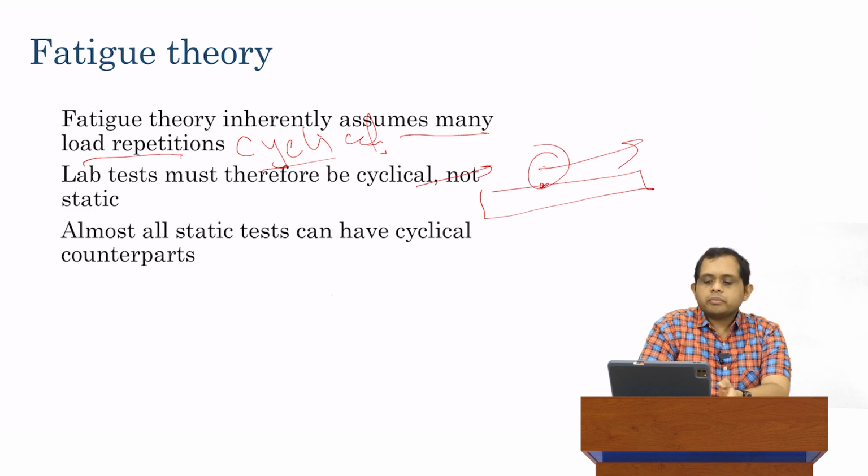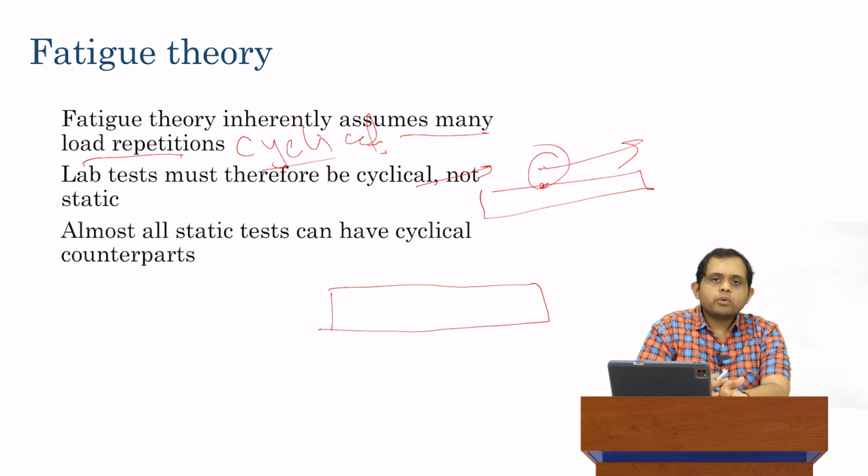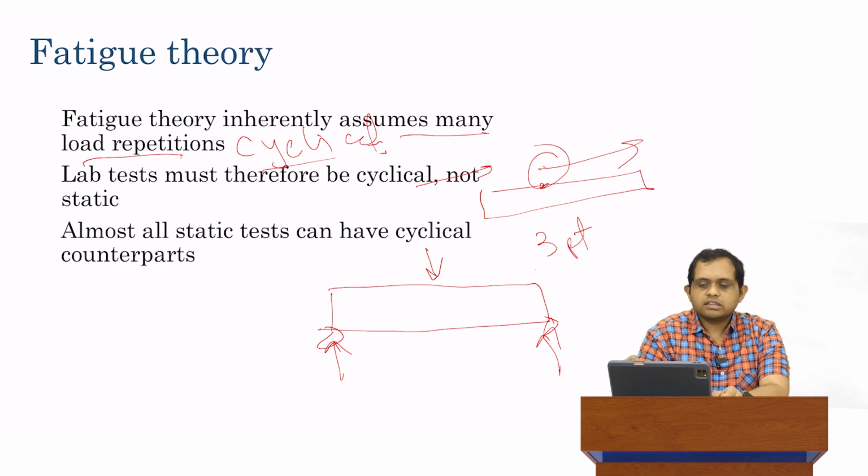How is flexural strength measured? Well, if you recall, there are two methods basically. There's 3-point bending and there's 4-point bending. So if this is a simply supported beam, some standard shape and size, those are all specified in various standards. We could load it in the middle. This is what we call 3-point bending. 3-point because the two reactions or the two supports give us the 2 points and the point of loading is the third point.